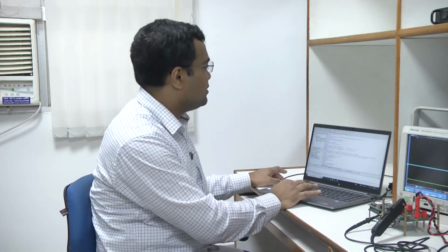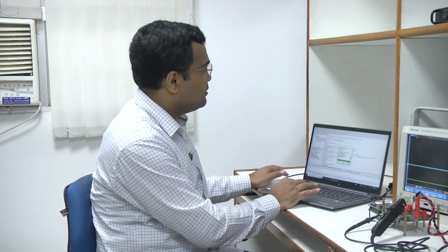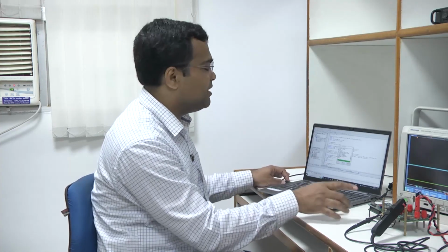Now, we are going to show the live demonstration of voltage based constant on time control, which is typically used for light load discontinuous conduction mode, where we are trying to improve the efficiency. So, it is also known as pulse frequency modulation, because we have discussed that the switching frequency will linearly vary with the load current. So, in this we have already run the code, we have synthesized, and then we have generated the program file, and we have loaded the FPGA file dump into the FPGA.